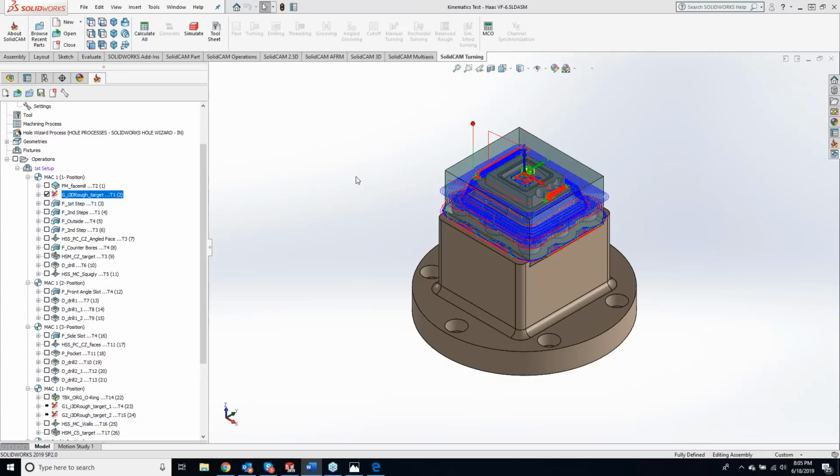Some of these where we move over to line segments, for instance, like a Haas with iMachining, we'll get some machines where the look ahead just isn't far enough, and so the machine will actually get a little jittery. So I'll show you guys how to accommodate that tonight and go through all the different fine tuning settings to get a smoother toolpath. Okay, so the first one we're going to cover is the iMachining one.